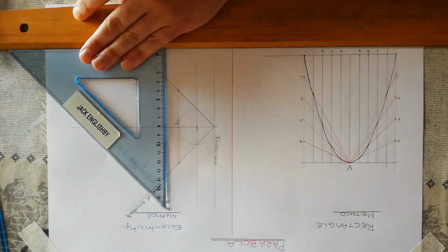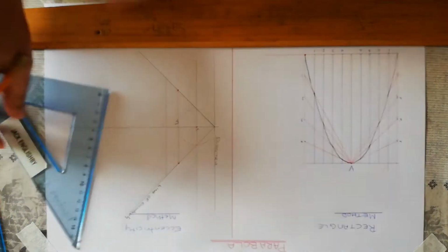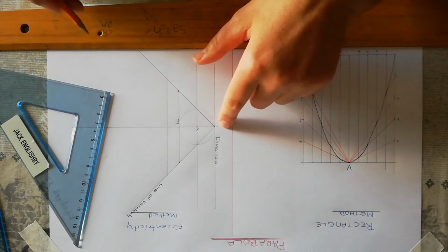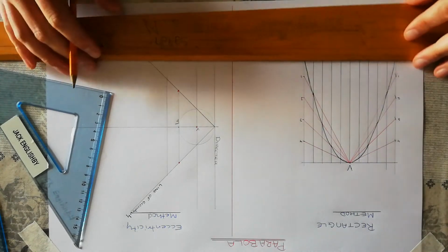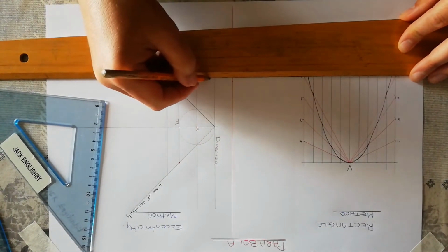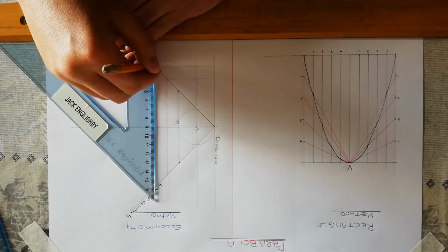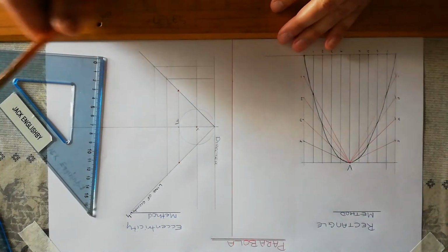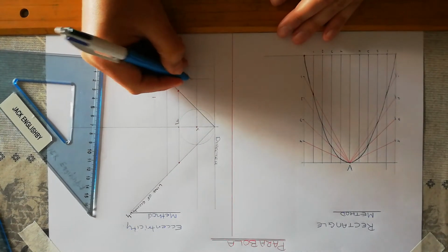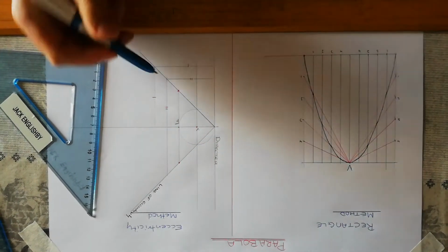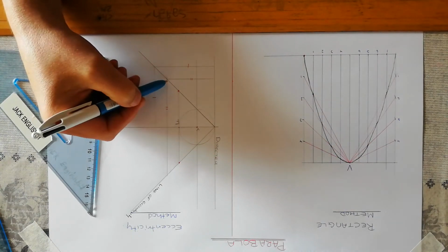Okay? So if we draw the line here, for example, now we know that their line's parallel, and we know that that's at 45 degrees. So we would be correct in saying that if I kept drawing these lines out like this, and they kept hitting our line of eccentricity, then this distance here would be the same as this distance here. And this distance here would be the same as this distance here. However, that distance there can't be correct because it's further away from the focus.